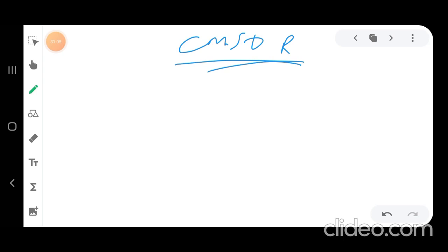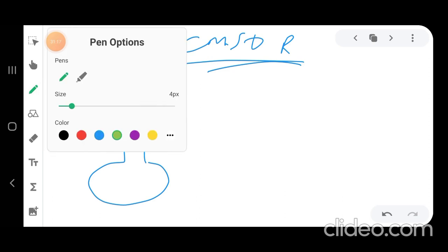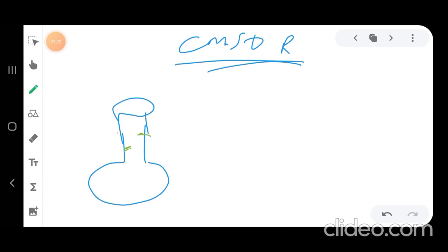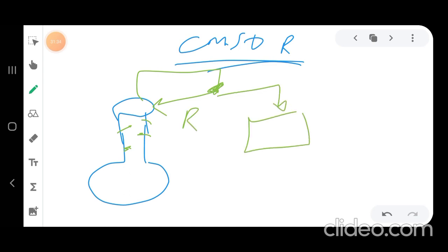We are going to make an assumption here that we have a constant boil up. What do you mean by boil up? Again, you have here your still pot, but now it is rectified. Rectified means we have some stages here. In order to maintain constant contact between liquid and vapor in these stages, you need to draw some reflux back, and then you take your product. This will be your product, you collect it in a tank or whatever.